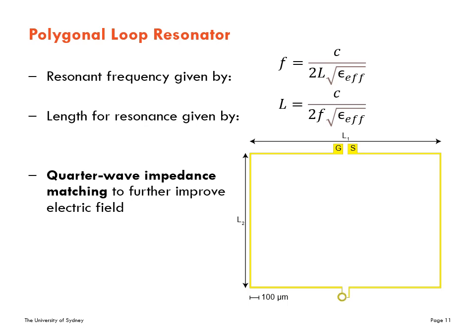The resonant frequency occurs when the loop is equal to a lambda on 2 long transmission line, so we can match any arbitrary frequency by computing the effective dielectric permittivity and using these formulas here. To further improve the electric field and reduce return loss, I used quarter wave impedance matching techniques to match the input impedance of the loop resonator to a standard 50 ohms. Since the resonator's input impedance is purely real at resonance and is already inherently narrowband, the narrowband operation of the quarter wave matching section is suitable.